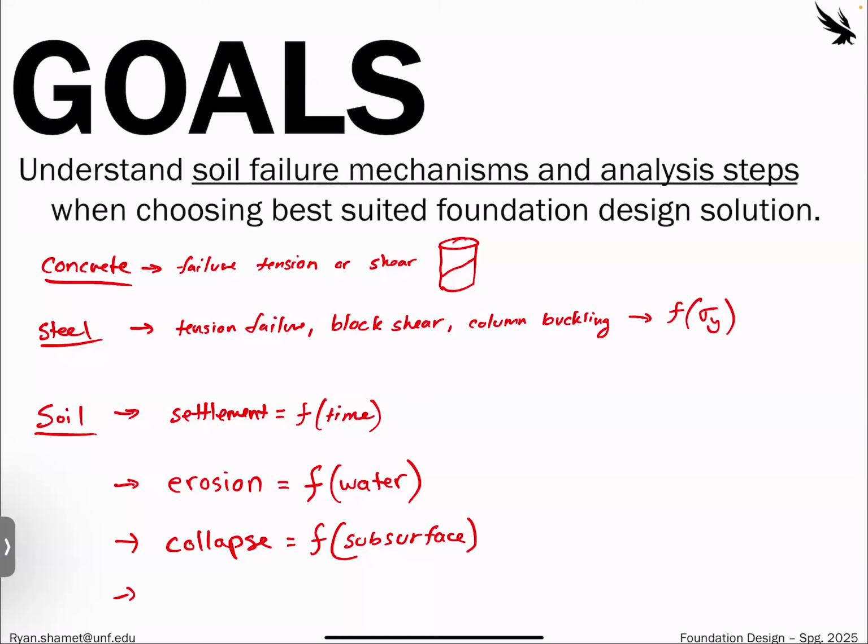The other type, too, that we'll see, the biggest can of worms, is the shear failure. So soil is individual particles, right, that are all interlocking with each other. And we talked about this in Geotech 1, but the way soil fails typically, like how you would say concrete shears, soil also, that's the main mechanism of failing as well. There is enough pressure that the particles decide to roll over on top of each other. And that particle rolling then pushes the other particles, which pushes the other particles, which then causes a failure plane to develop and then causes the whole thing to move.